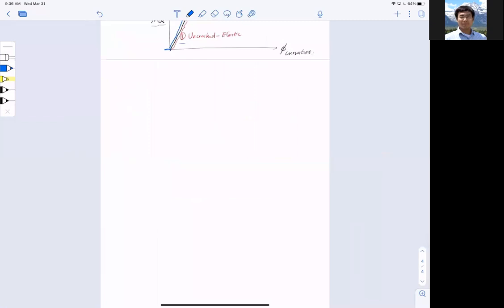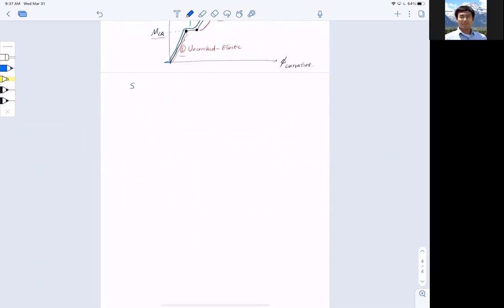So that is the concept of how we deal with deflection. Like I said in the previous section, it all comes down to how we determine the Young's modulus and moment of inertia for the section. You start to think about it: for the uncracked section, it's not that bad. Stage 1 is uncracked, elastic. And for moment of inertia, all I have to do is take a look at the section.